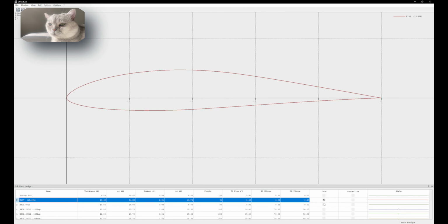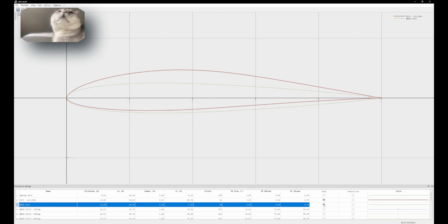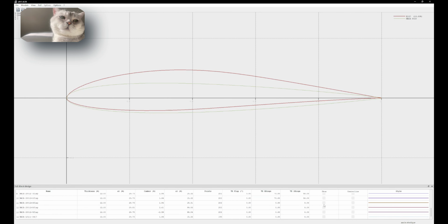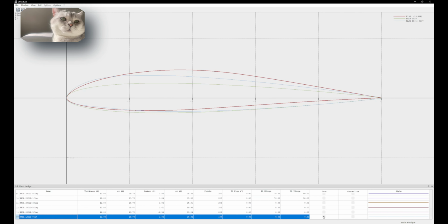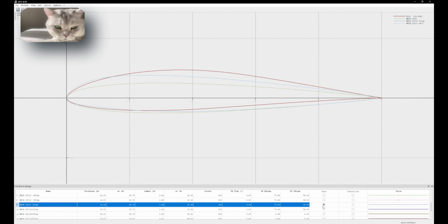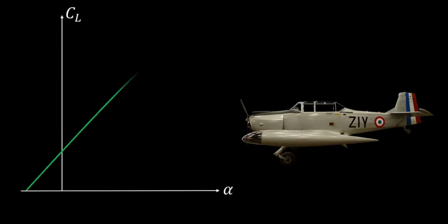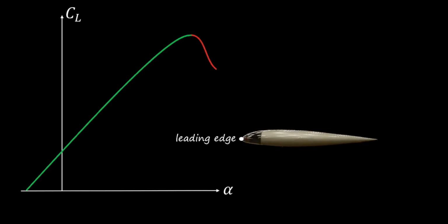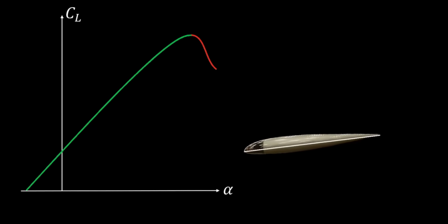After verifying that the preliminary model performs without major issues, the next step is the selection of a suitable wing configuration. Several common configurations used in light aircraft are chosen for initial comparison, followed by further screening. Once all models are imported into the analysis software, attention is focused on key parameters such as the lift coefficient, lift-to-drag ratio, pitching moment coefficient, and stall behavior.